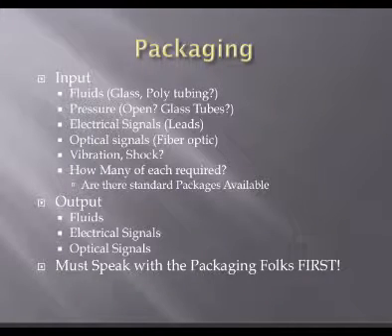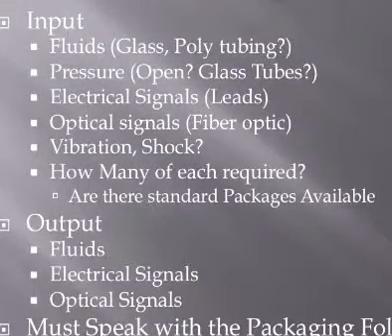Okay, so packaging is important. You have a lot of different inputs: fluids and pressure, electrical signals, optical signals, vibration and shock. Those are all different kinds of environmental inputs. And then how many do you need? Is there a standard package you can use? That's really critical. If you can find a standard package to put your MEMS device in, you're going to save about a year's worth of work to get your product to commercialization.